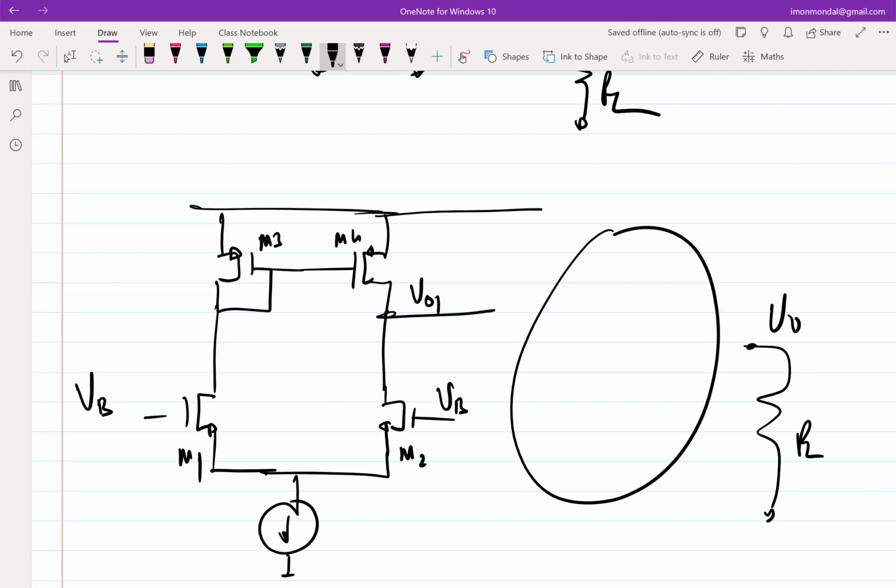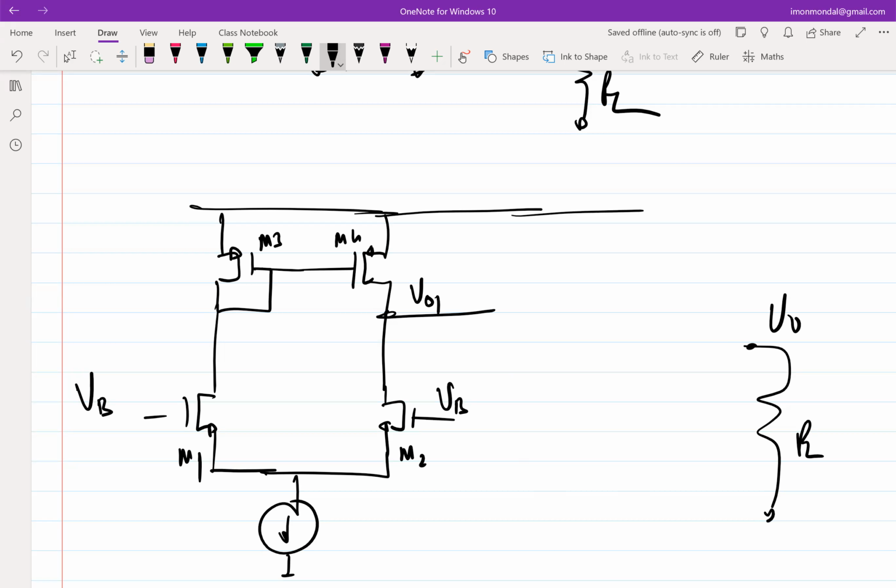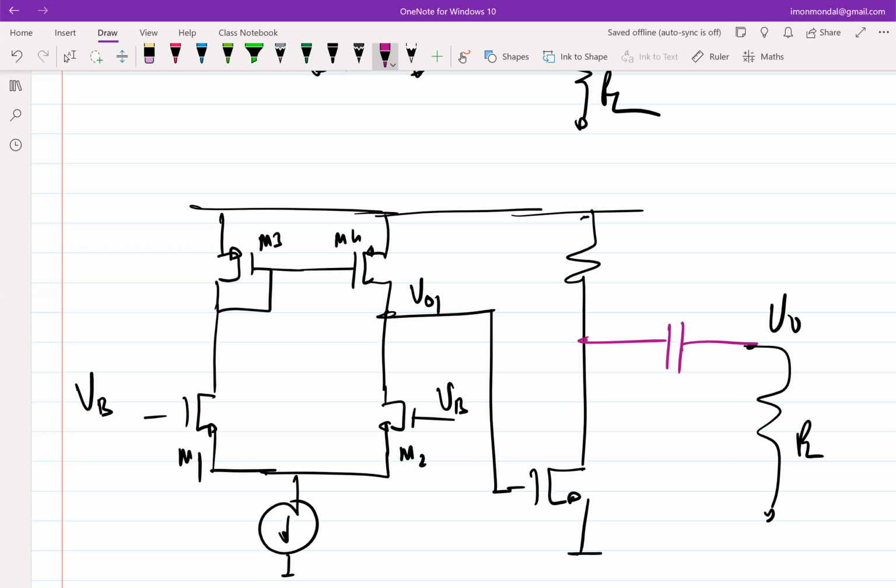So now we have two options for a common source amplifier: a PMOS based common source amplifier and an NMOS based common source amplifier, right? So what will determine whether I should put a PMOS based or an NMOS based common source amplifier? Let's say I use an NMOS based common source amplifier, which means I'll have something like, I mean, let's start off with the resistive load, then we can also do the current mirror load. So this will go here, right? And there's probably an AC coupled output that's allowed if the spec says so.